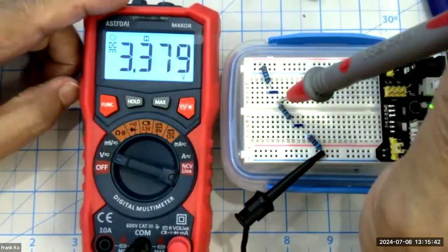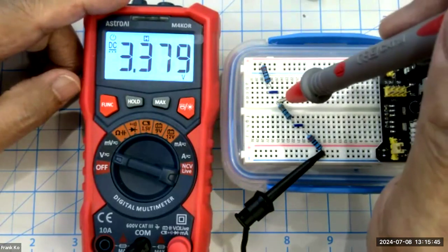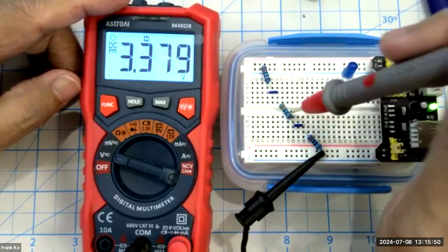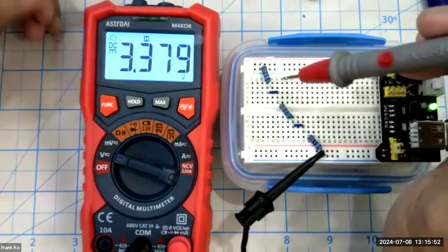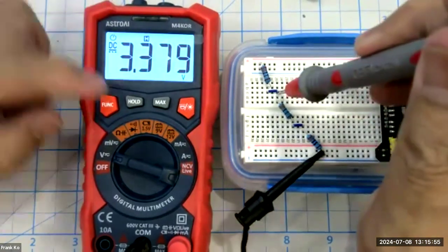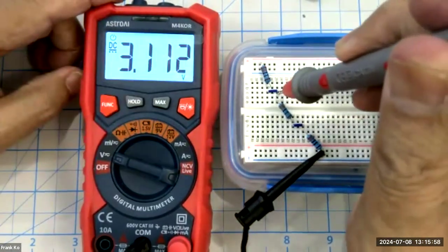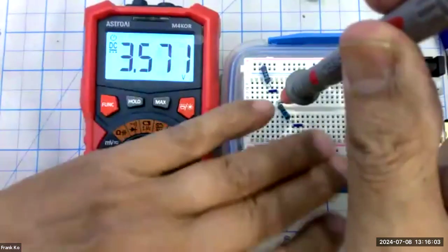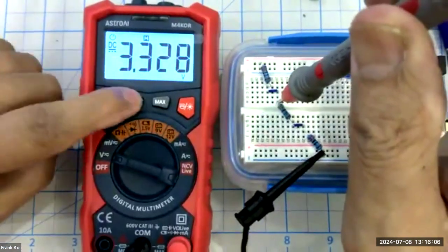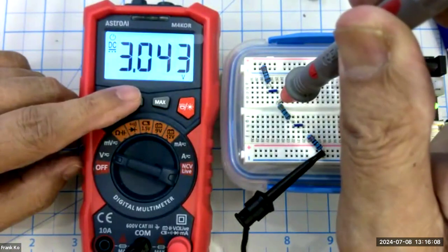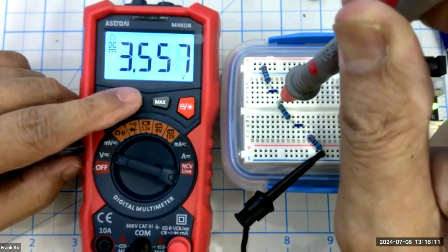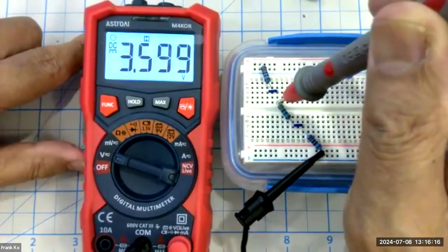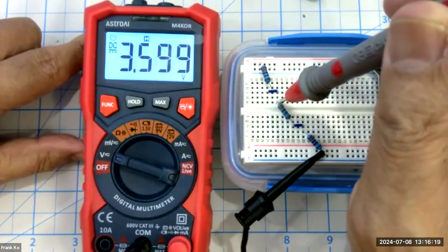Okay. 3.3, not as close to 3.57 as we would have liked, but again, there are some resistances on the board, maybe some contamination, certainly some tolerances to the resistors. Are we somewhat close to the 3.57 volts? And let's go ahead and do this one here. Put this down, and it will land on it eventually. All right, so 3.599 is almost 3.6, pretty close to 3.57.